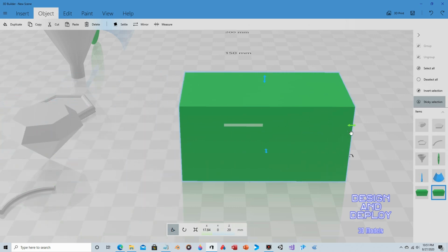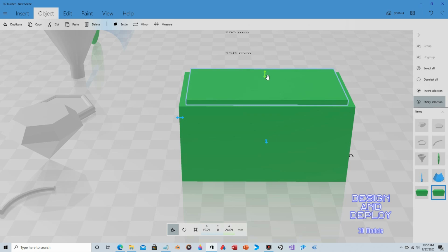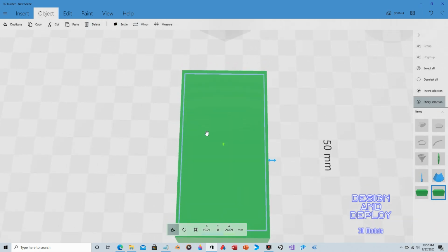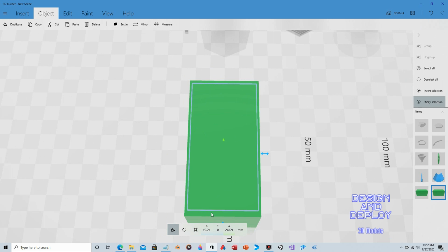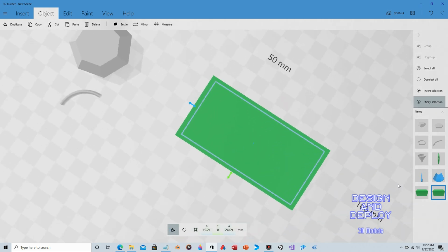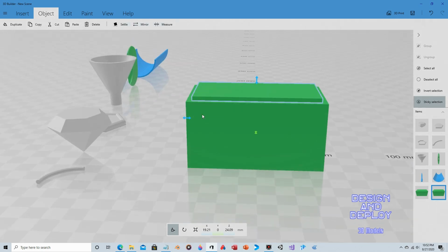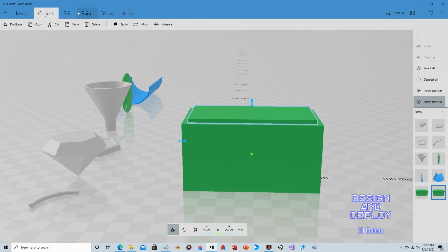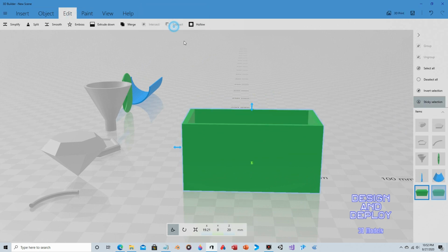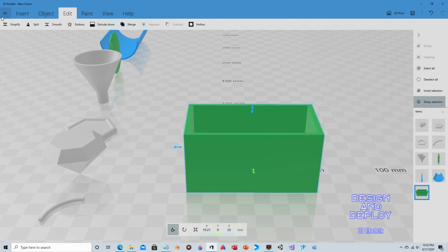And we'll slide this over so it's centered. We will shrink it in all directions by using the white dot in the corner. We'll raise it up. So again, we're going through the top. Now, because it's a rectangle, the edges are not the same thickness, so you may want to manually try to true this up. And then recenter it. Okay. And again, you want the top protruding out. Edit and subtract. So there's the bottom of your treasure chest.